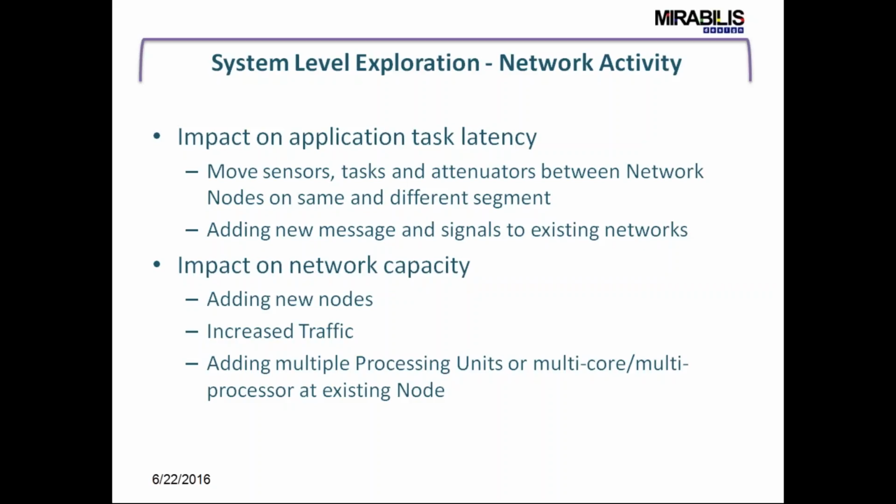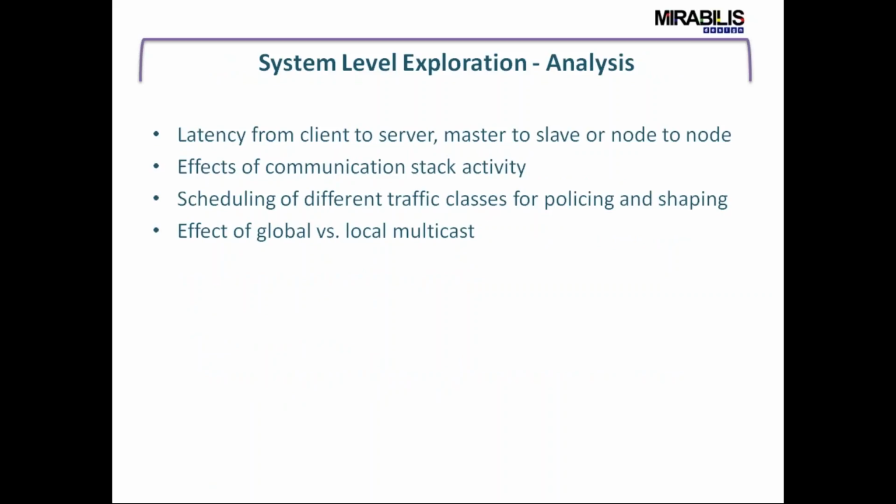Okay, so you can explore your RapidIO based model or TTEthernet based model using system level exploration to identify the kind of problems you could expect during implementation. Typical analysis reports that you could expect out of a simulation model to select a particular technology would include the latency that you're getting. So definitely your RapidIO should return latency in terms of microseconds.